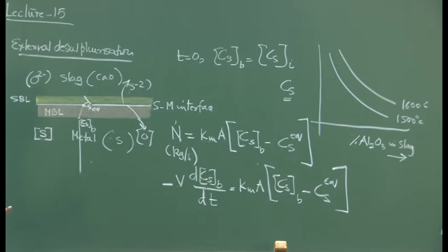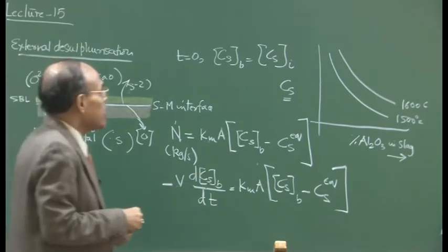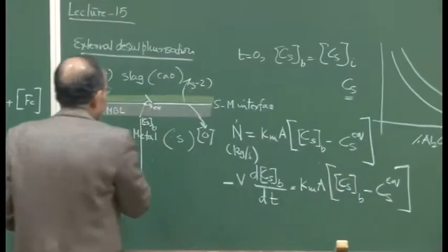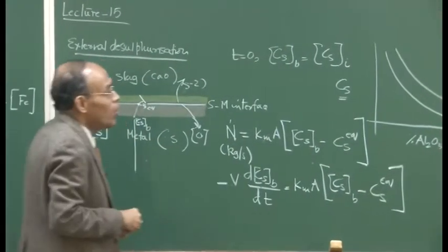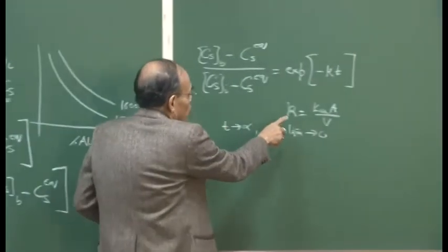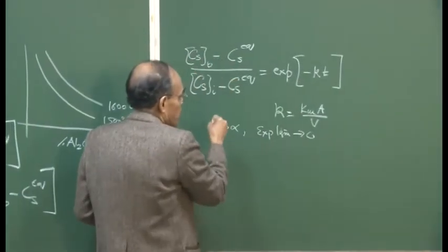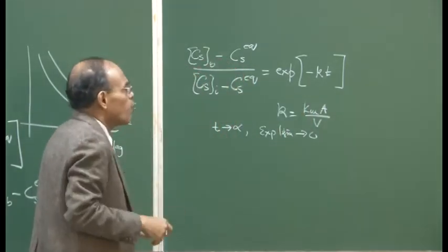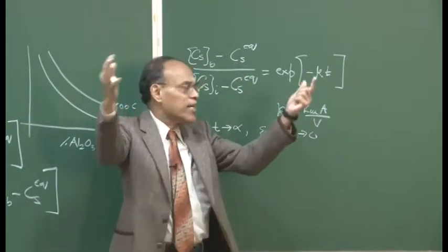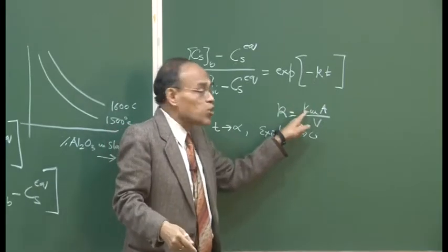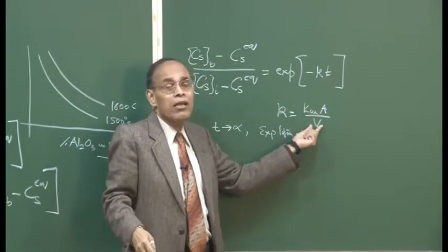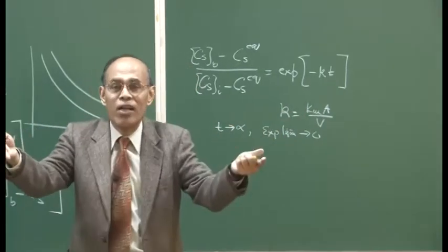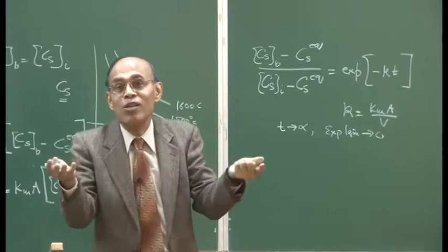Now, this Km is the melt phase mass transfer coefficient. So, we will require a good amount of study in order to have a higher rate constant value, for high rate of sulfur transfer, we require a higher mass transfer coefficient. So, the volume is almost fixed because the reactor size is fixed, but these are process parameters. When desulphurization will be done in the industry, either in a torpedo car or in a ladle, those ladle volumes are not going to change.